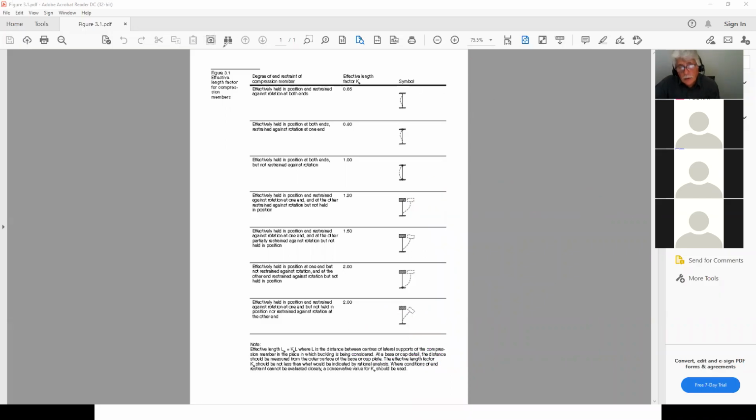So if anything, we'll talk about this any time that you guys want. Like I said, if an element can take the lateral loads and you know that you can rely on it, by all means, just make sure that the path that you're creating can actually bring the loads to that point, and then they can be resisted there. That's what you have to think all the time. What is the load path? In other words, how is the load going to transfer from this point to that point? Like you have a beam, you have a load.